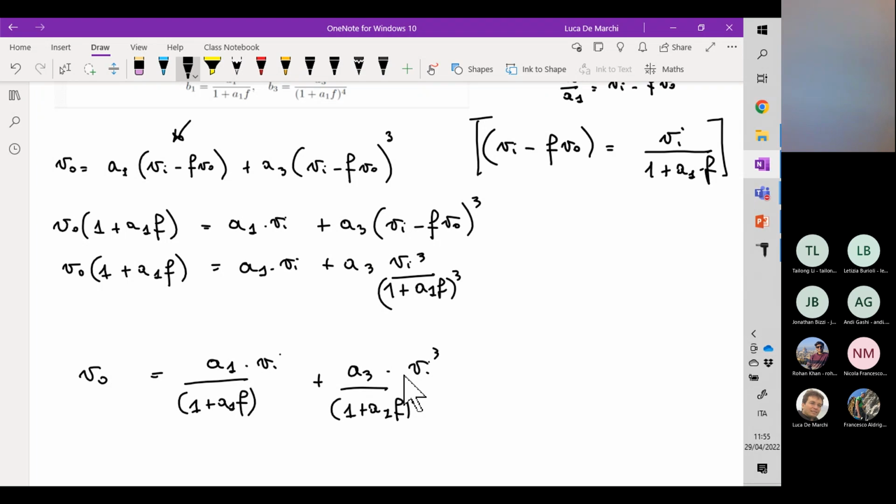These considerations are illustrated also in the next slide. So distance x, this drop here from the value of A of j omega modulus with respect to A null, is the direct measure in decibels of the loop gain magnitude, the absolute value of T of j omega.